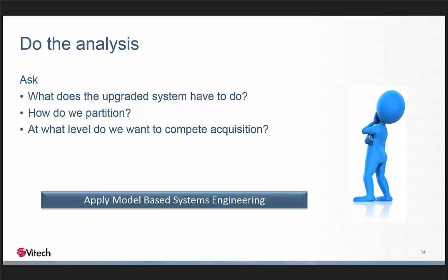Again, what is it that they want to do? Can they go off and compete something at a much lower level? Do I have to compete with the supplier base at the whole radar level, or can I go down and just replace the amplifier? Well, from my experience, we found out that the traveling wave tube is a really great mechanism, but it requires an extremely high power supply. When we go to the solid state, you can have multiple pieces, multiple sub-power supplies that are summed up to get you to that maximum power that achieves the range requirements. So we found out you can't just swap out the tubes, you have to swap out the tube and the power supply. So those things are intimately related. We're going to have to do both at the same time.